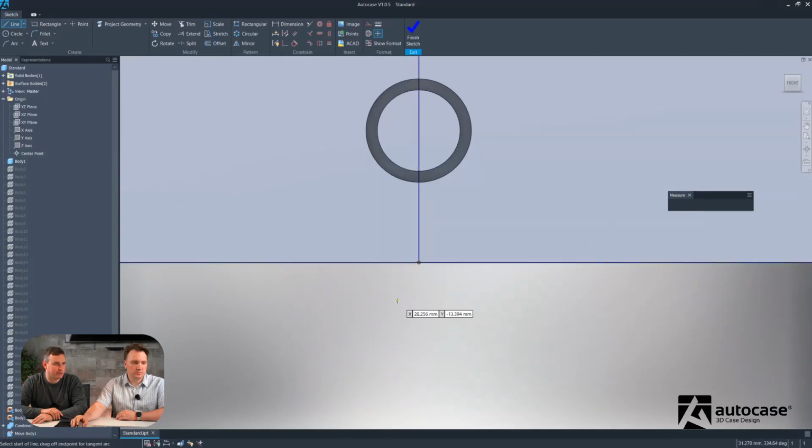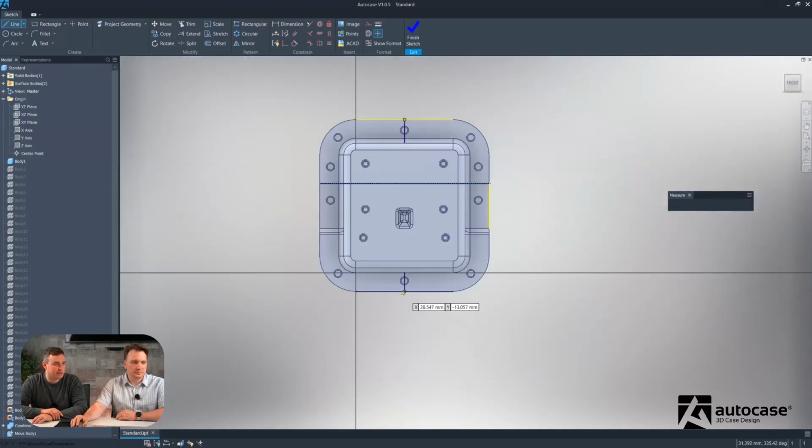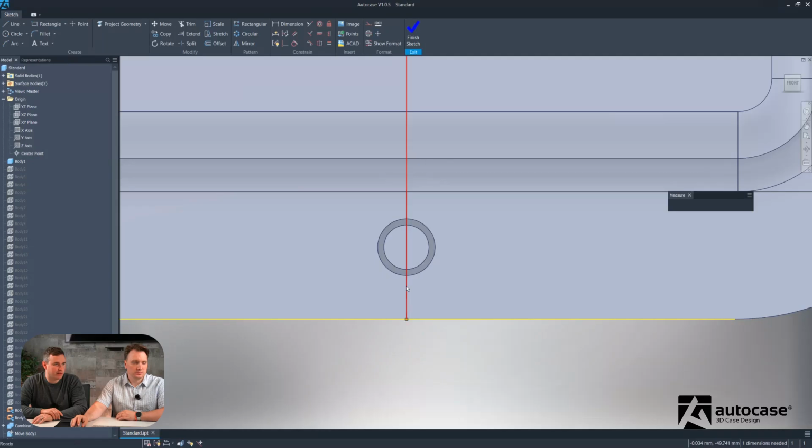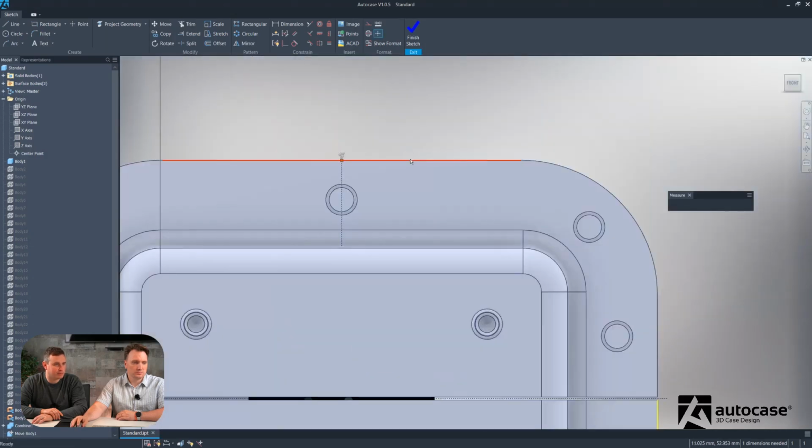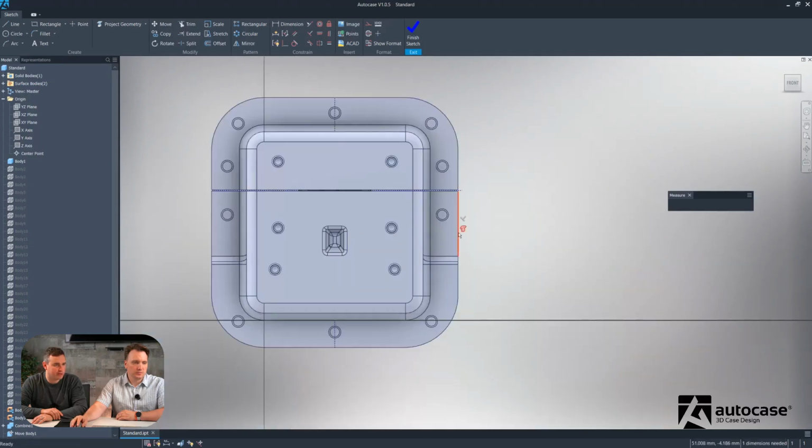and it'll go green. You can also see that you get 90 degrees as well. So we can turn this into a construction line by clicking on that line, turning that into construction line and then locking it. That will put it locked in place. And then as you can see, as we've created that construction line, it's created additional geometry where it connected. So we can just, again, remove that and just double check there isn't another one. There it is at the top. And whilst we're doing that, we can see we've got one other one that's been created along the edge there.